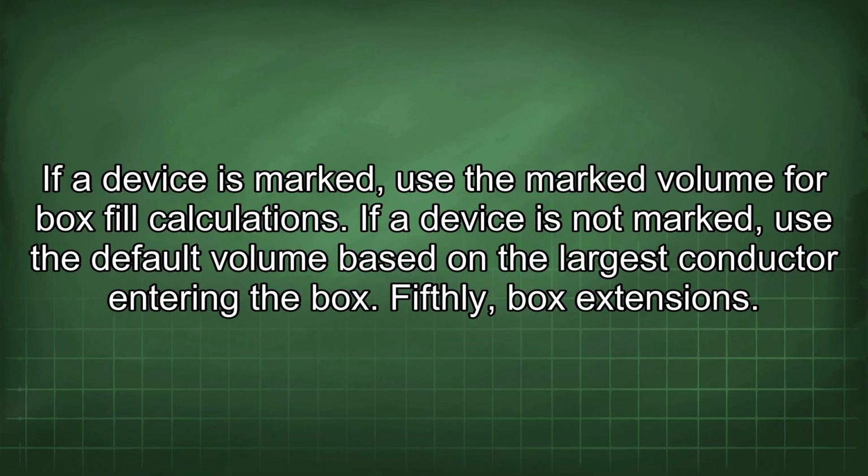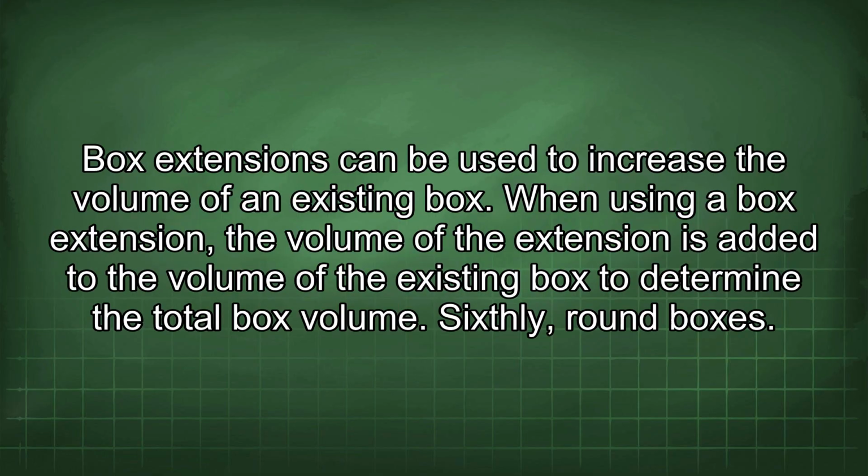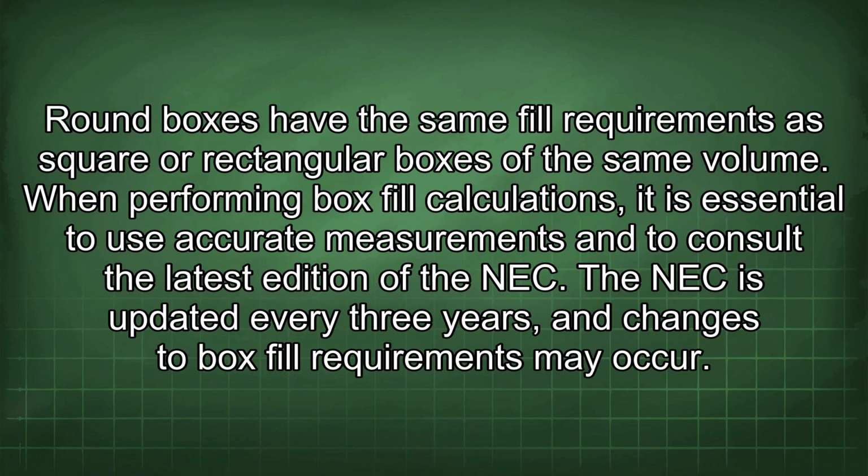Fifthly, box extensions. Box extensions can be used to increase the volume of an existing box. When using a box extension, the volume of the extension is added to the volume of the existing box to determine the total box volume. Sixthly, round boxes. Round boxes have the same fill requirements as square or rectangular boxes of the same volume.